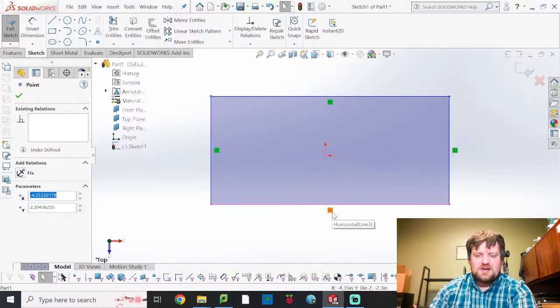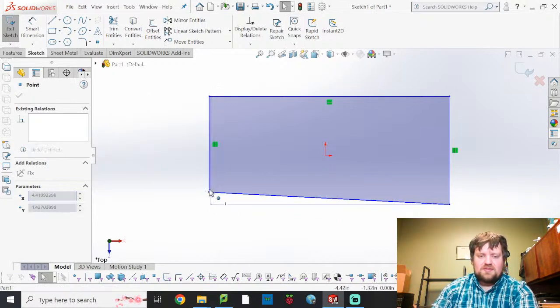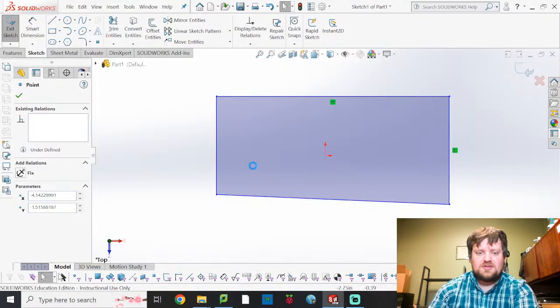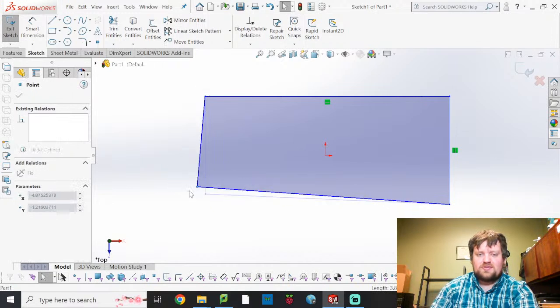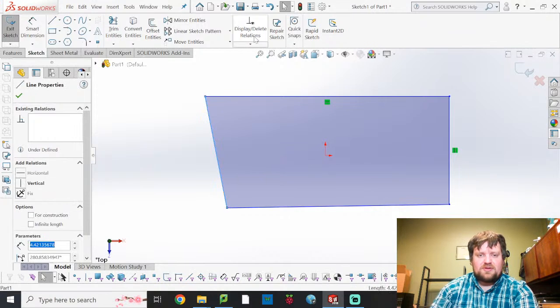These are called constraints. If I click on it and delete it, you'll notice that I'm able to actually move this, and now this line is no longer horizontal. If I click on this one and delete this one, this line is no longer constrained to only be vertical. So if I move this point out, it'll just rotate out. Okay, that is in effect what relations are.